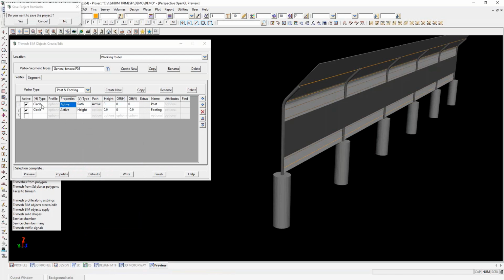You now want to take this horizontal shape that you've got and then extrude it, for want of a word, along a pathway. Now that pathway can either be defined as a height, in this case a height for the footing, or you can actually have drawn a string that represents the path of this bent post. So the choices you have are height and path.